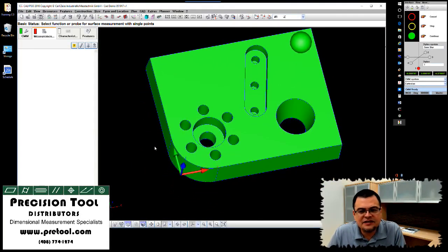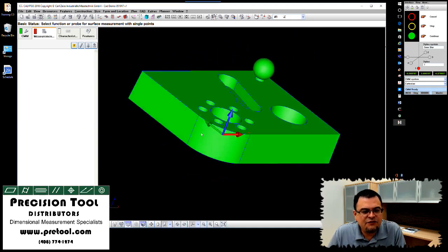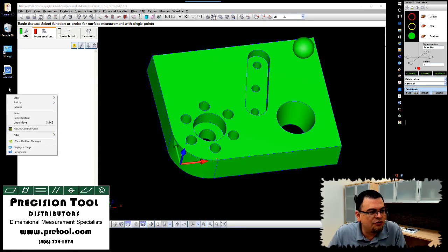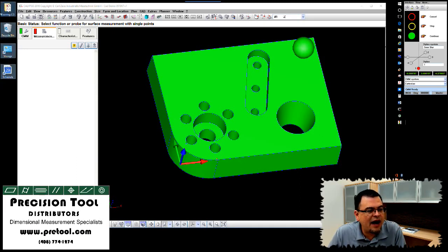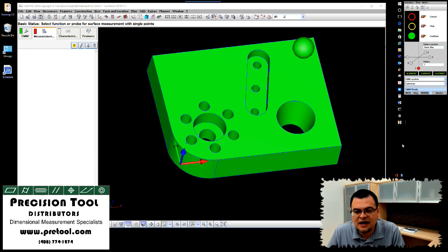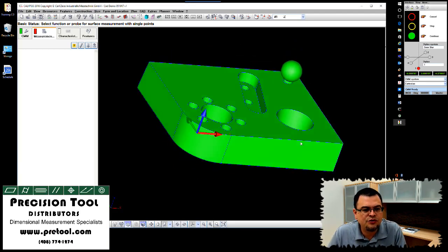Now, a couple things, and these are kind of minor details. If you find yourself slowing down or bogging down with your CAD model, make sure you do things like get rid of your desktop bitmap, minimize the number of icons that are sitting on your desktop, get rid of any arrow themes that you're using from Windows 7, 8, 9, or 10, depending on what you're running here. I guess there's no really 9 that anyone used, at least.